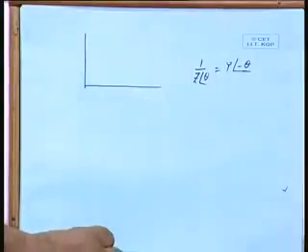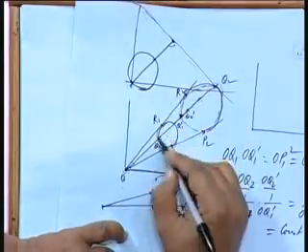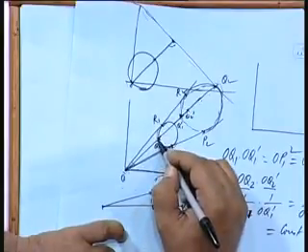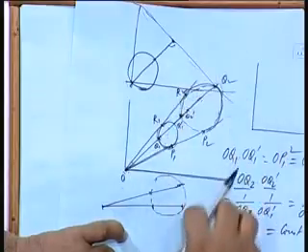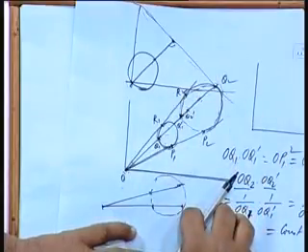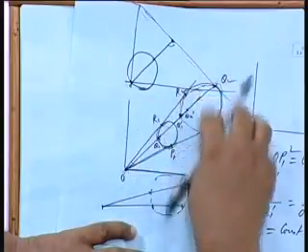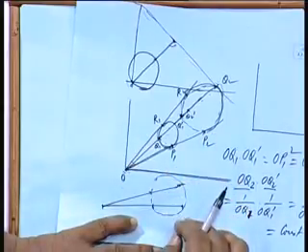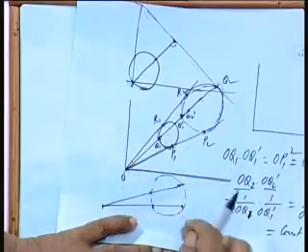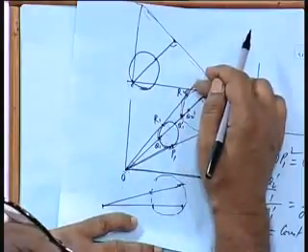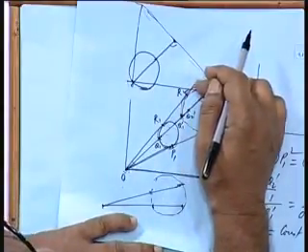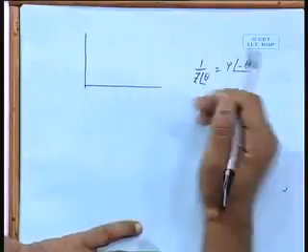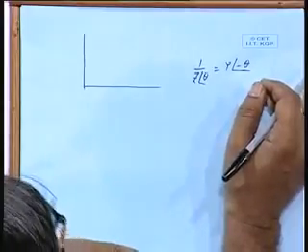So, whenever we are inverting a circle here, if these represent the phasors or impedances, then this should come in the other quadrant. So, first quadrant quantities will be reflected in the fourth quadrant. Similarly, if it is R minus jX kind of impedance function, fourth quadrant quantities will be taken in the first quadrant, all right. So, this is to be taken care of when we handle any problem on circuits.